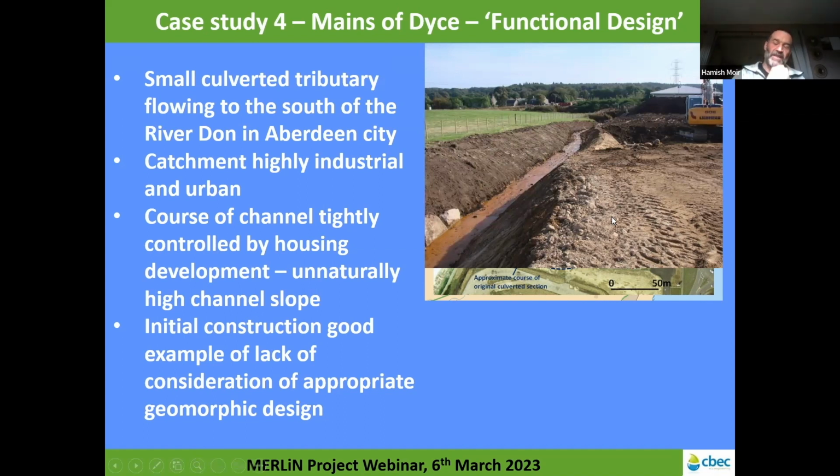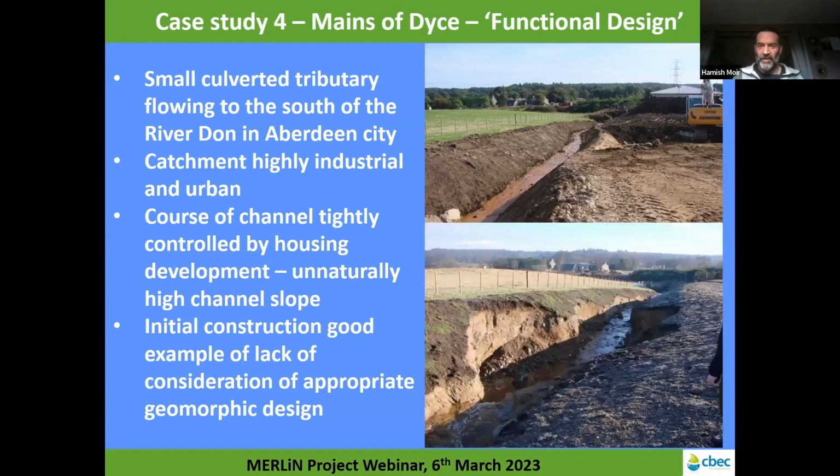The contractor didn't agree with us, just wanted to keep this channel. And so, just through poetic justice, there was a flood event about a week later, and the channel ended up looking like this. So there's been a head cut. Erosion started at the bottom here and worked its way all the way upstream. There's a bit of a waterfall structure here, and all this material is gone. You can see it's obviously an entirely unstable site now, not appropriate for a channel adjacent to housing.